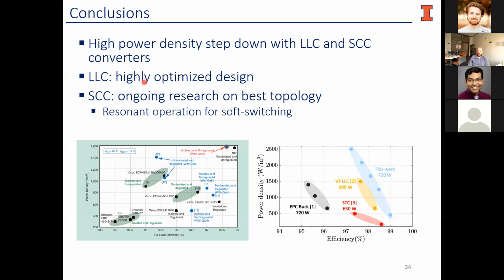When it comes to how we look at these designs right now, I think one of the really interesting things to look at is the thermals, right? When it comes to a lot of mean time to failure and failure analysis, a lot of it comes down to thermal characteristics of the devices. And you can see a very strong correlation: the hotter these devices are running, the more failures we'll see. And there are some very well-known breakdown mechanisms in silicon as far as temperature. Many of the other components also have these very specific curves when it comes to temperature and